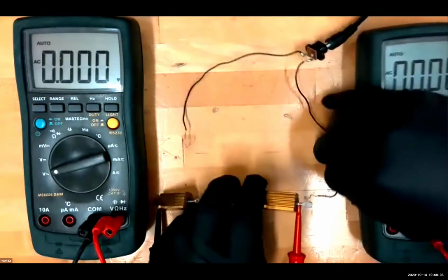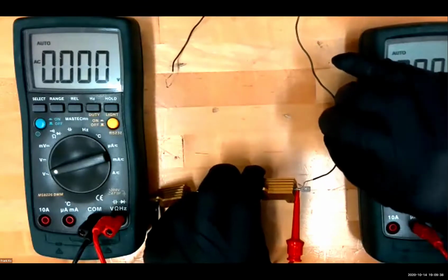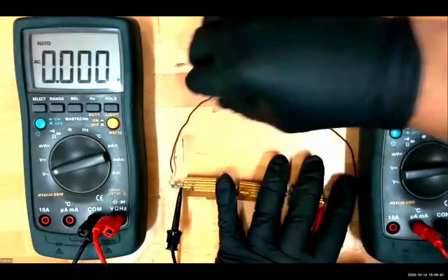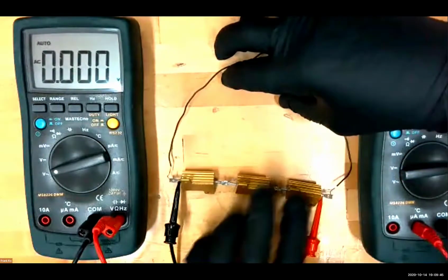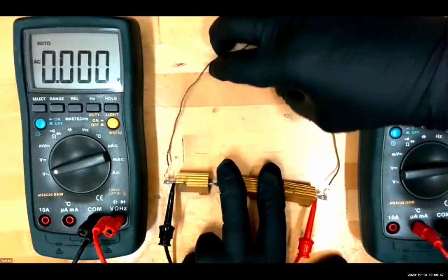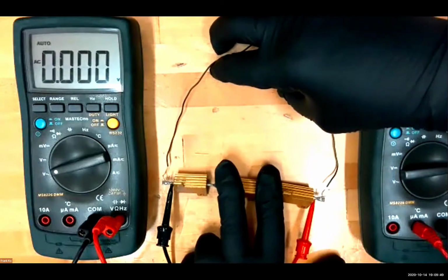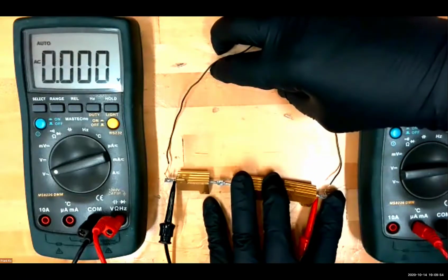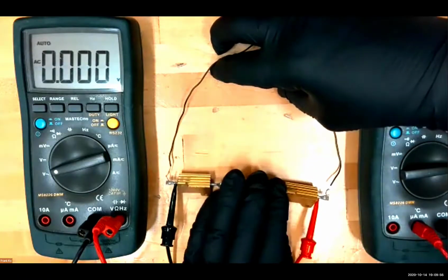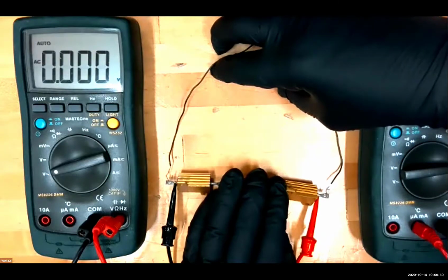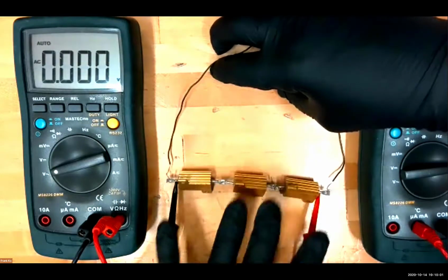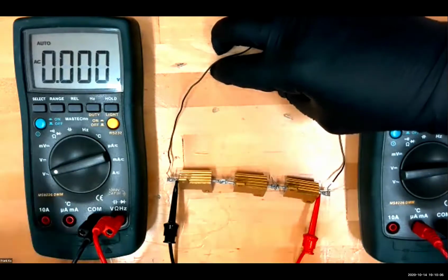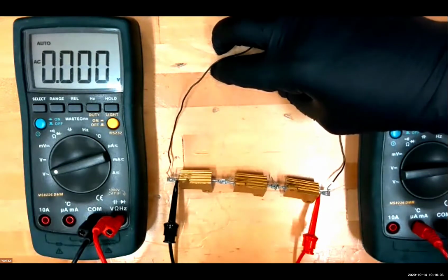When I go to hook up my wire for this side, and I go to hook up my wire for this side. So if this were on, and I'm giving a little bit of tension here by pulling on this slightly, and that way I'm guaranteeing I have good electrical and mechanical contact of the wires on either end, I'm going to be able to get current through these resistors and be able to measure a voltage using these connections to this meter, yes?